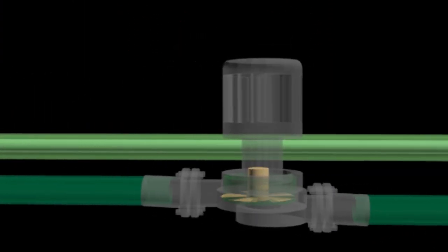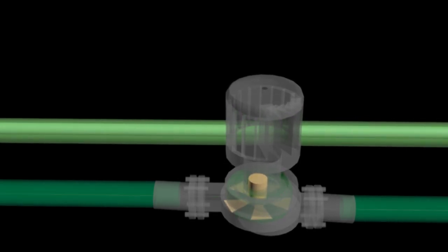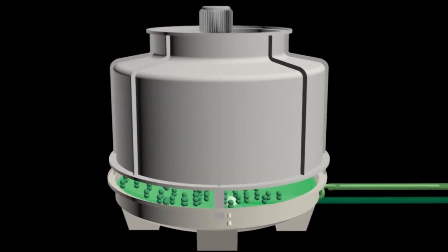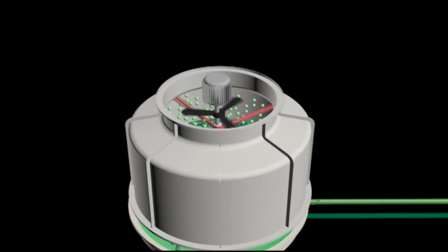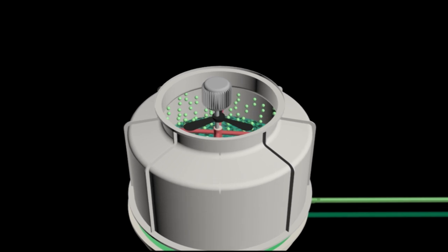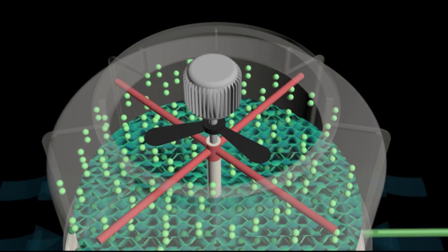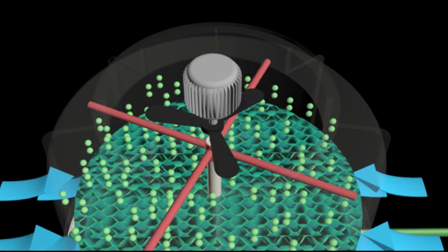From the condenser in the chiller, condenser water flows to the cooling tower with the help of a centrifugal pump. This water is called condenser water return. This condenser water will pass through the rotating sprinkler blades on the cooling tower. These rotating blades use pressure generated by the condenser water itself. Water will gush down through the fins to reduce the speed of water going down.